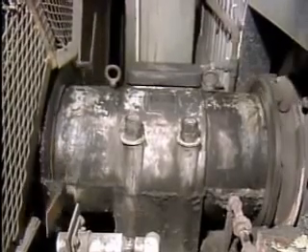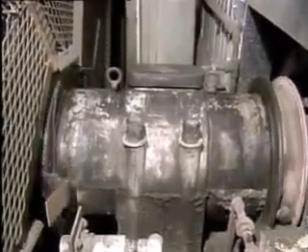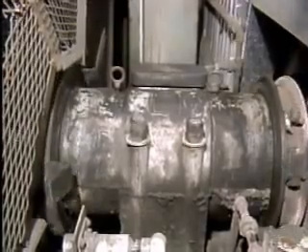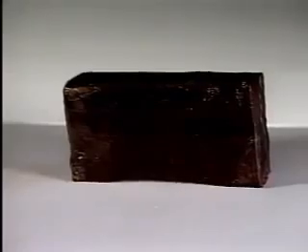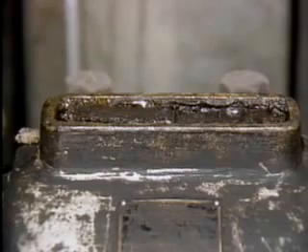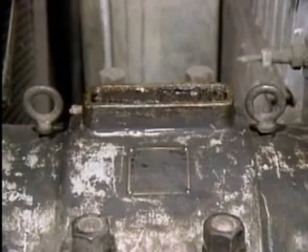This shaft, for example, turns a device that rotates through the hot gases produced in a boiler. The hot shaft turns in a sleeve bearing in this housing. The shaft and the bearing must be lubricated with a grease that will stay in place under high temperatures, like this hard grade 6 grease. A block of the hard grease is placed directly on the shaft through a hole in the housing and the bearing. The heat will cause the hard grease to melt, but only enough to lubricate the shaft without running out of the bearing.